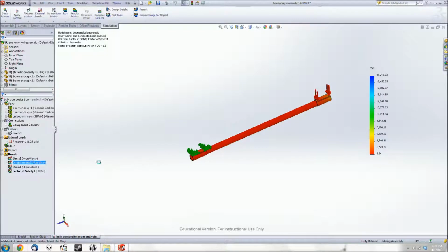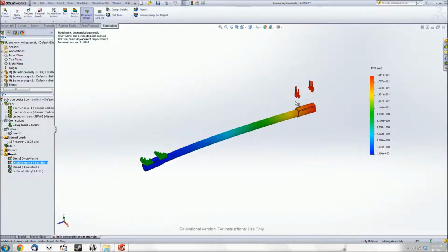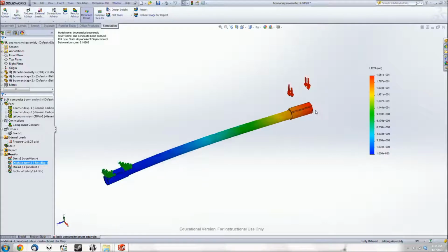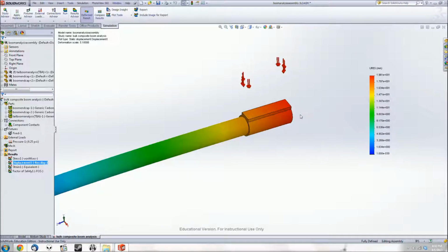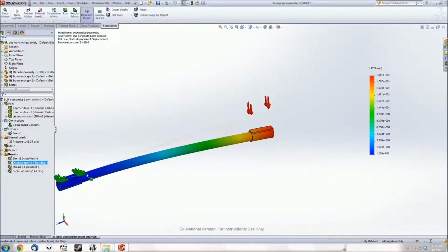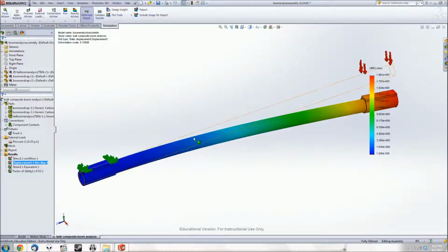Also, something you'll note, this displacement looks huge for not that much pressure, especially for a relatively sturdy carbon fiber beam. But look at the actual scale here. This is only 19.6 millimeters at its worst spot. So it's almost 2 centimeters. That's really not that bad. This is exaggerated heavily from what it actually looks like. So just be aware, don't just take the picture at face value. Actually go through and look at the numbers on the graph and see what's actually going on.